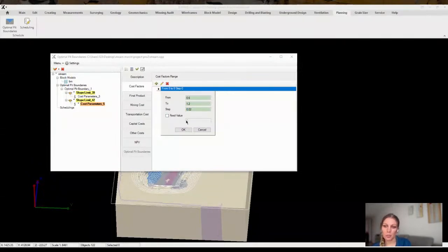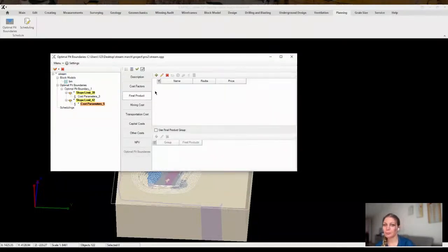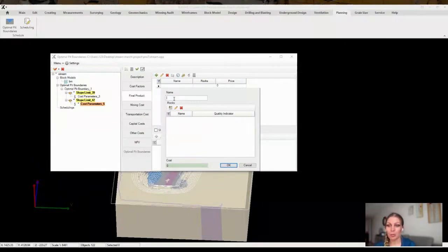And let's create a similar scenario with a slight variation. This time we'll choose an angle of 42 degrees as the resulting angle of the pit for rocks and leave all other settings unchanged. To make a reliable comparison, it's essential to repeat all the scenario settings accurately. So we should aim to compare apples to apples and avoid matching several scenarios with variation in several data points.